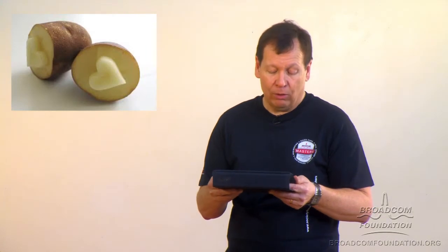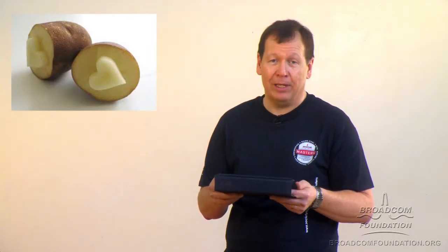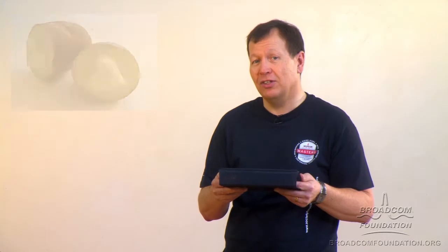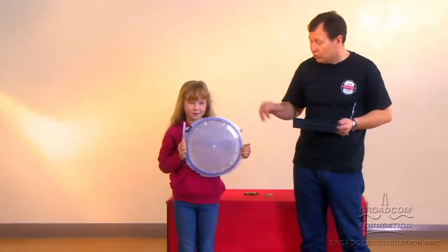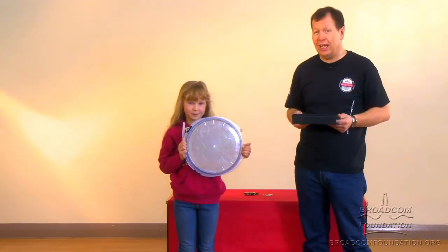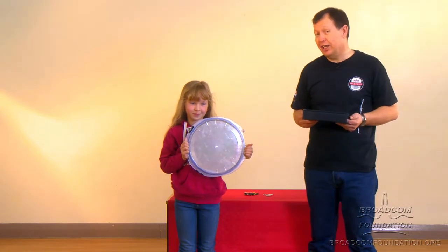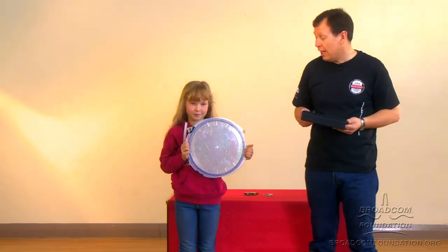With this integration, it produces a lower system cost, higher reliability, and better quality of devices. Now, to make multiple devices is a bit like using a potato stamp. We take one design and we copy it many, many times onto the silicon wafer. And this has got thousands of copies of the same design stamped out repeatedly across its surface. And when they're all finished, a very sharp saw is used to cut each individual circuit out and then package it so that it can go into the gadgets that you use today.